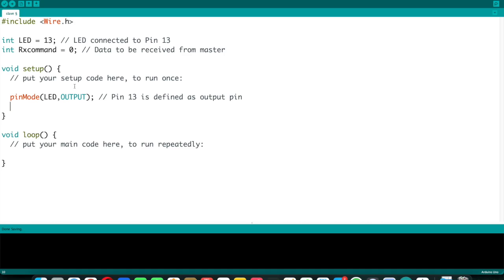So in order to print something on the serial monitor, we need to write Serial.begin, and definitely S must be capital, Serial.begin(9600), to use the serial monitor. As I told you, Serial.begin is a serial communication. It uses 9600, which is the baud rate. The baud rate is 9600 bits per second. It's a convention rate that two systems can communicate with.